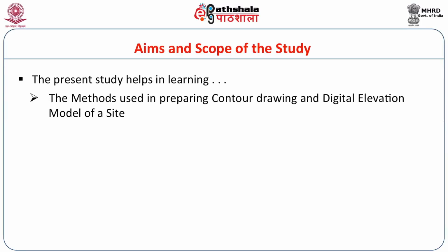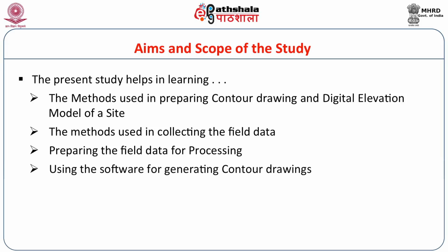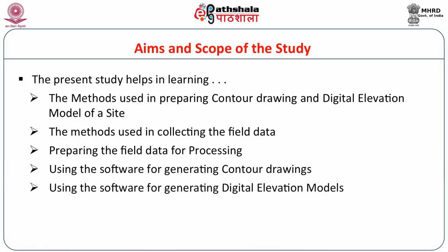So, in this module you are going to learn how to use the instrument dumpy level in taking the elevation readings, and how to make the entries in the data sheet, and then how to input the data, field data, into the computer program, and then how to generate contours as well as elevation models using the field data.